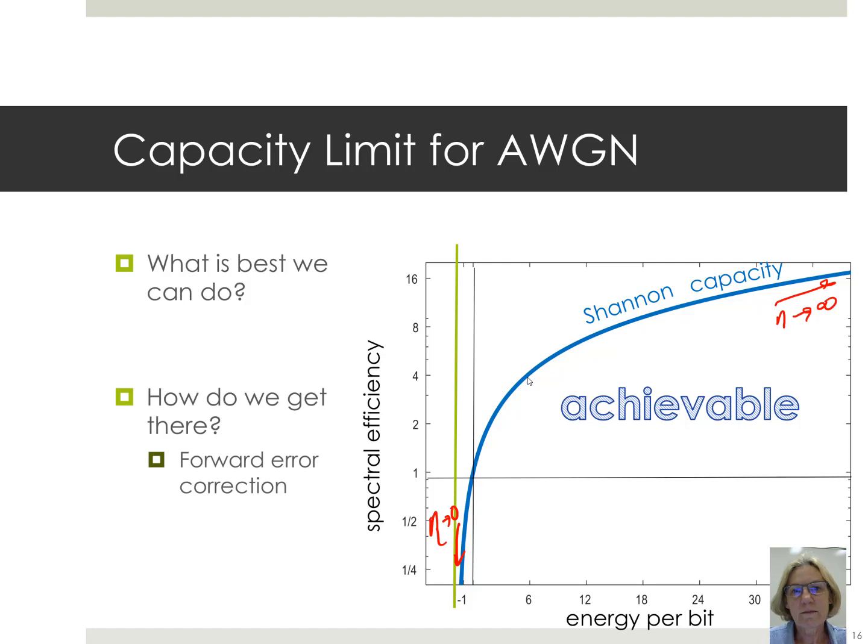In the end, we've developed what we call forward error correction, which is digital signal processing that allows us to add redundancy to data in a structured way so that at the receiver we can actually use the redundancy that we've added to correct errors as they occur. And I tell people that for me it's almost like magic. I can look at a signal which is so corrupted by noise that it seems impossible to decode it, and actually by running some DSP we can have the signal pop out with very good reliability.